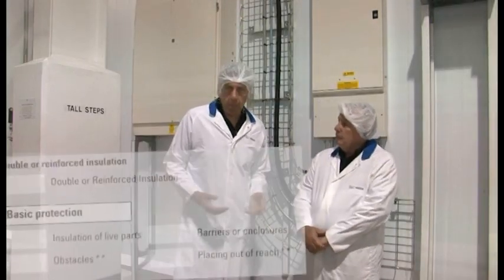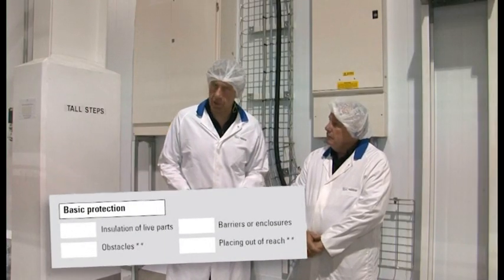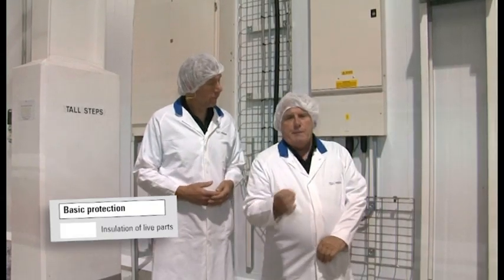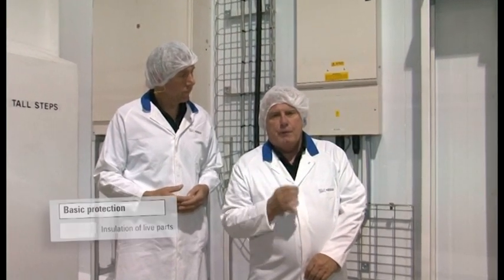Moving on to the next heading, we have methods of protection against electric shock incorporating only basic protection. And the first of these is insulation of live parts. Quite a simple one, this. Throughout the installation process and upon completion, it's important to check that any parts of the installation which will be live during service have not received damage to the basic insulation protecting live parts. For example, when installing cables, they can be damaged in a number of ways.